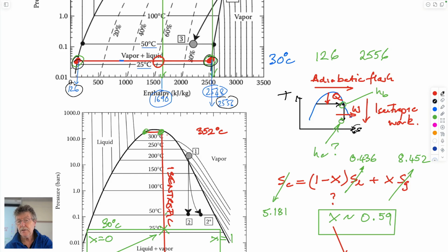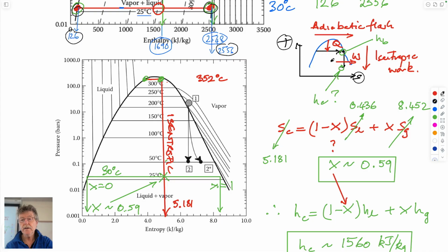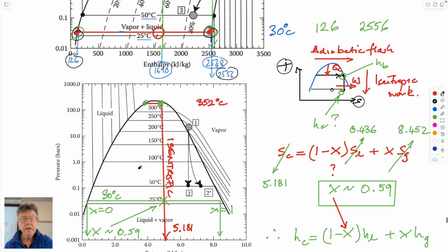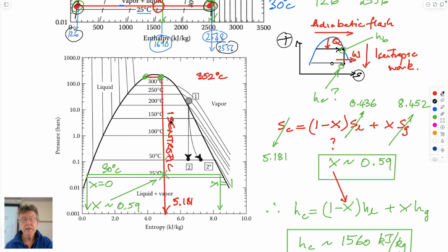So notably, this is written in terms of entropy and temperature, and not enthalpy and pressure. And so what we want to know is where on this lower curve we exist if we reduce ourselves without changing entropy. So if you draw this curve as pressure versus entropy, instead of pressure versus enthalpy, isentropic means the entropy doesn't change as it goes from one temperature to another. So it has to track along this curve here.